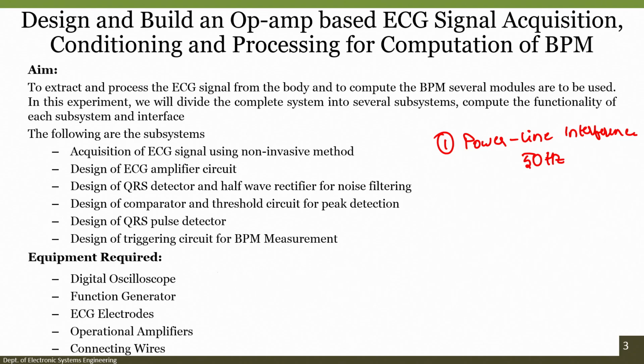That signal is not required. So, more than those frequencies, 50, 150 and 300, we may not require all these frequencies, right. One way to remove them is, in order to remove that particular frequency, we should know the frequency range of our ECG signal. Generally speaking, the ECG signal frequency will be somewhere around 0.05 Hz to 120 Hz, or generally they also say up to 100 Hz. So, this is the major operating frequency range of our ECG signal.